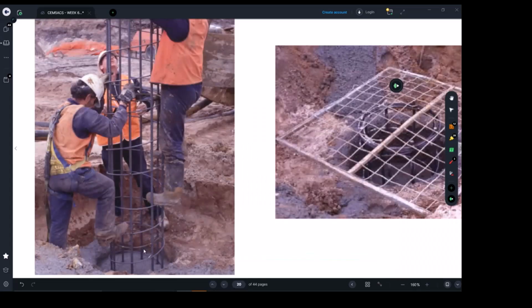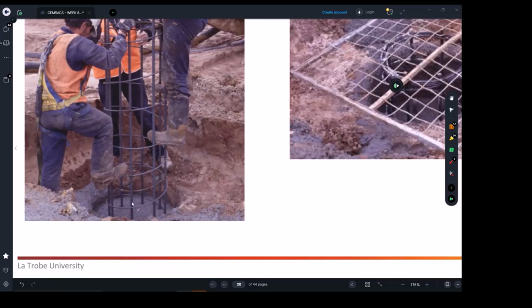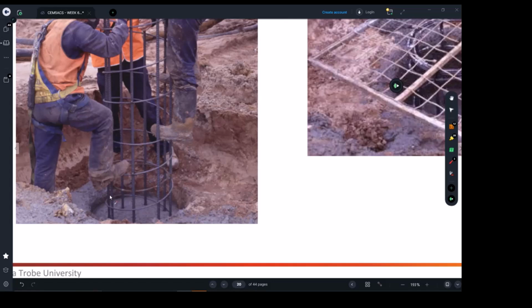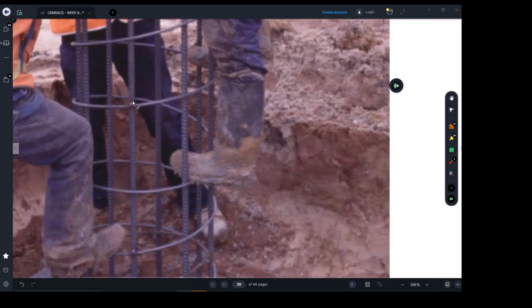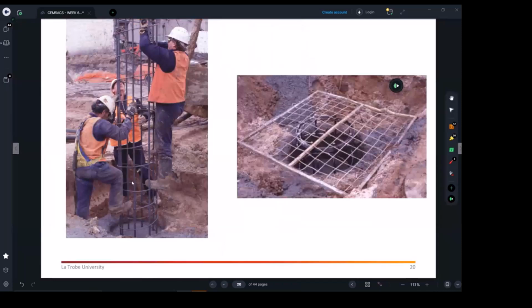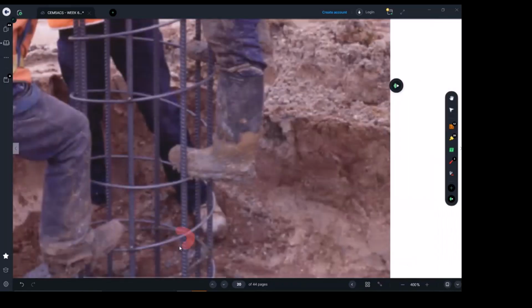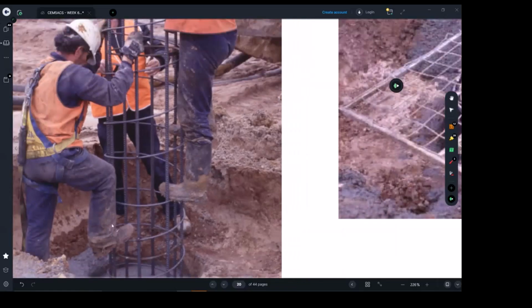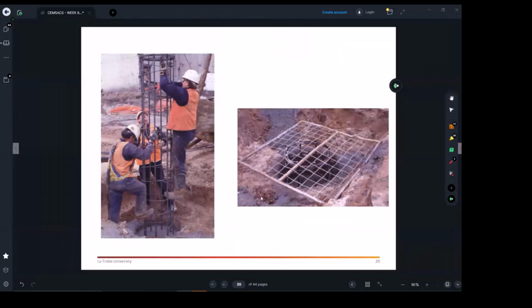As I said, for the key preparations, you need to know that your concrete is at the correct level of slump in terms of having super plasticizers. Slump measure is about 200 millimeters. And the reinforcement components are tack welded together to make sure. You see what they do to it. So definitely, you don't just manually tie it, because it may get displaced and things may go wrong. You know what we are saying here?